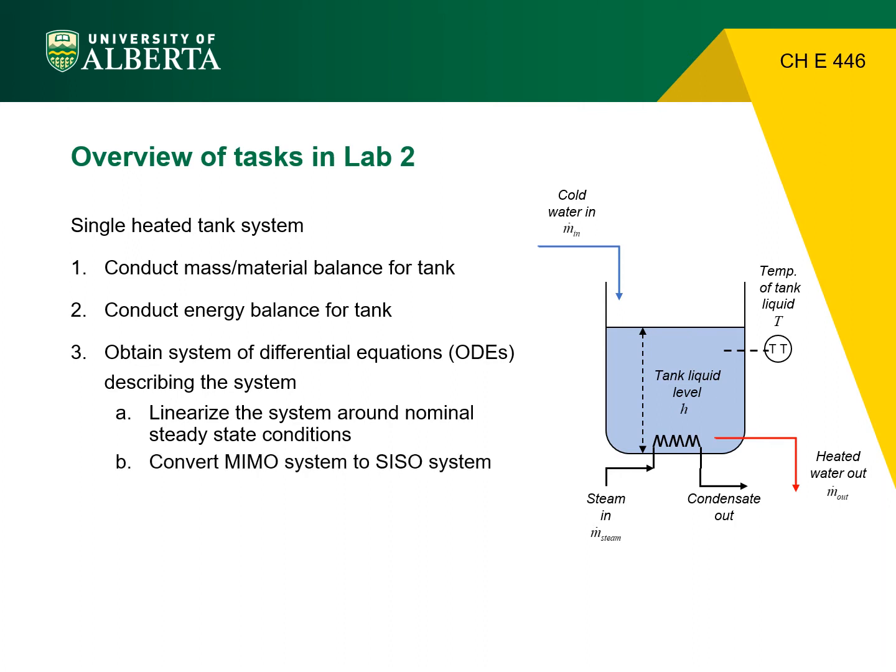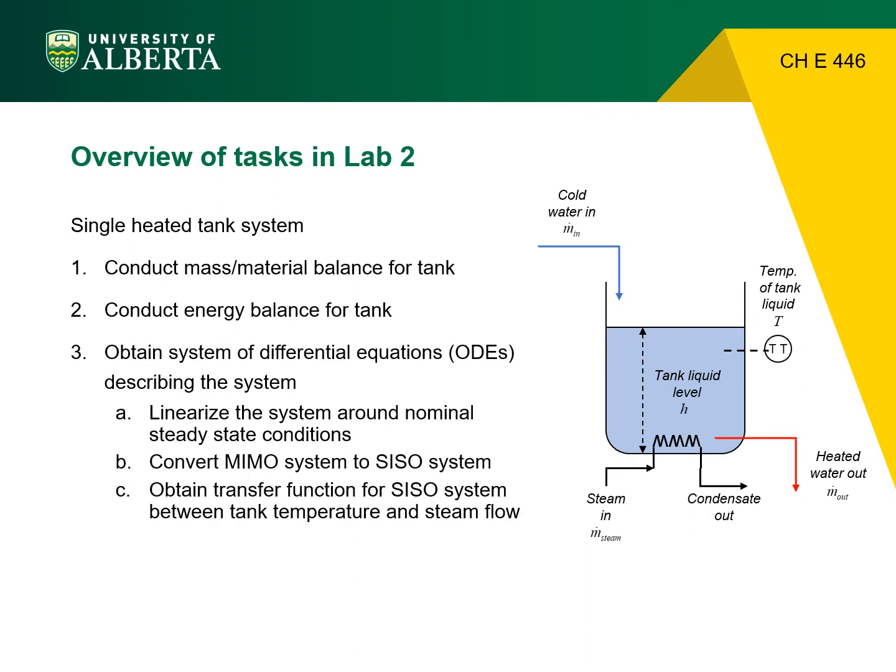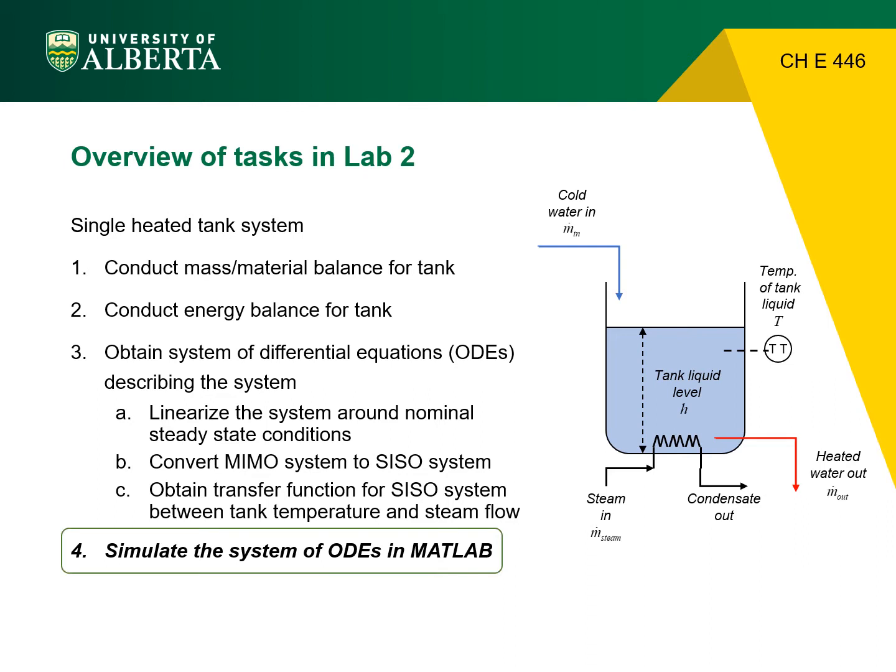You are asked to convert the resulting multi-input, multi-output or MIMO system into a single input, single output or SISO system. For the simpler system, you are asked to formulate it as a transfer function between temperature of tank liquid and steam flow. Finally, you are asked to simulate the system described by the ODEs in MATLAB. This is the main objective of this seminar.